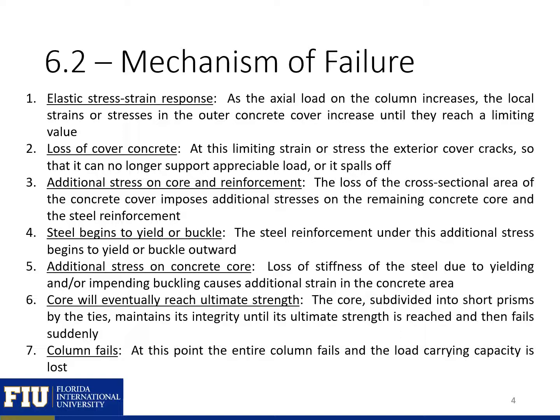At this time, the limiting strain or stress of the exterior cover cracks so that it no longer can support appreciable load, or it spalls off. So at step 2, we lose our cover concrete and we only have our confined core. Any additional stresses are on the confined core and the reinforcement.